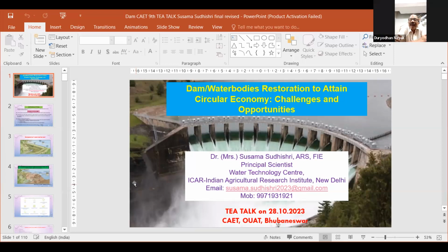Recently, I have retired. I have a little experience particularly in soil conservation and dam construction. As you asked, what is the ratio of catchment area and command area? Actually, there are so many parameters as Dr. Susama told. We know all, but on an average, we can say that it is maximum 10:1. Suppose catchment area is 10 hectares, we can maximum command 1 hectare. That is the approximate method so far we have adopted.